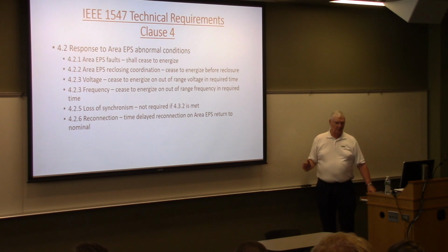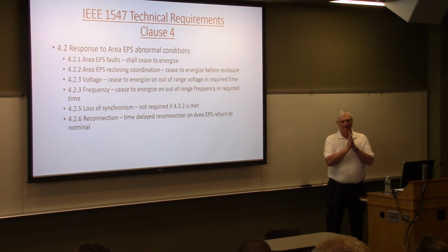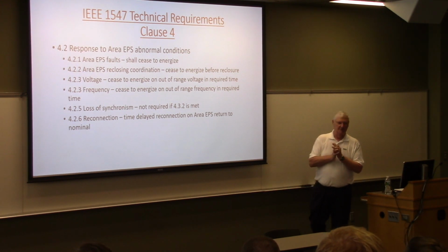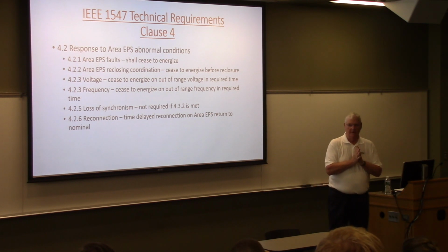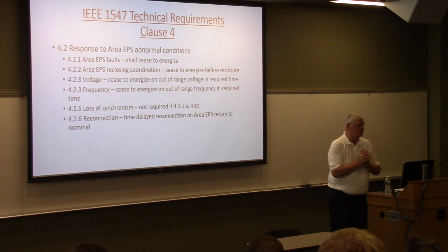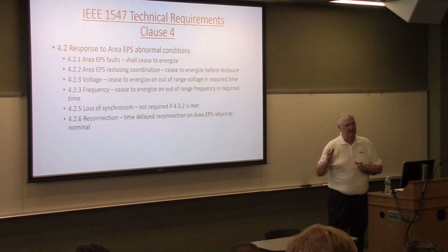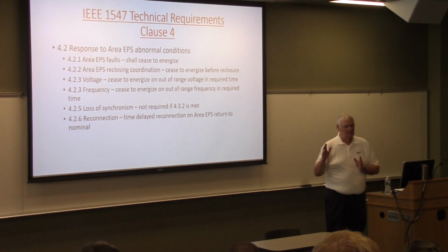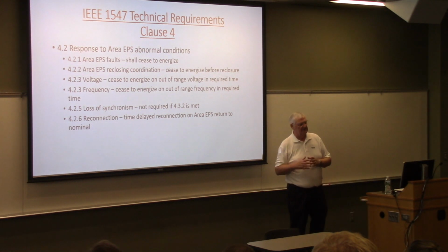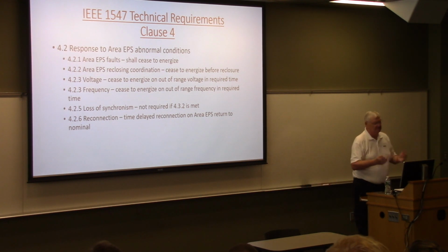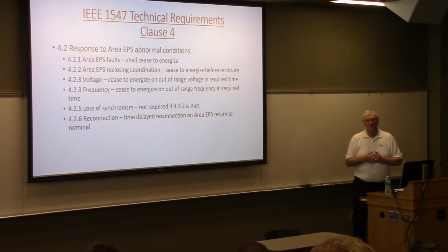It was also concerned with being within bounds on voltage and on frequency. There is a standard, ANSI, American National Standards Institute, C84.1, which says that a utility company is required to provide voltage at the point of common coupling within minus 10% and plus 5% on a regular basis, with momentary excursions outside of that to some limit. So if the voltage goes below the acceptable point, the original thinking was it should come off the line. Your distributed energy system should come off the line.